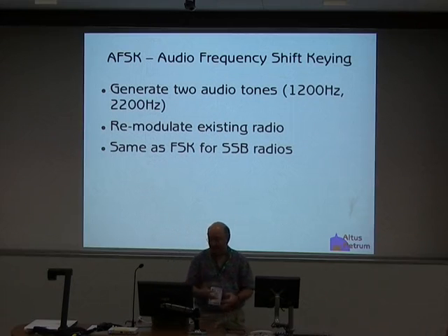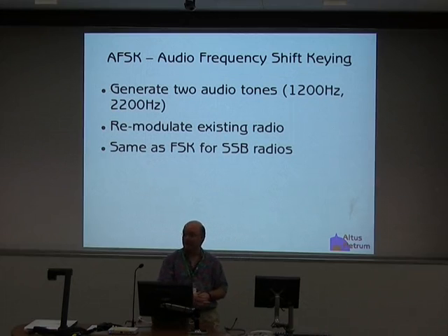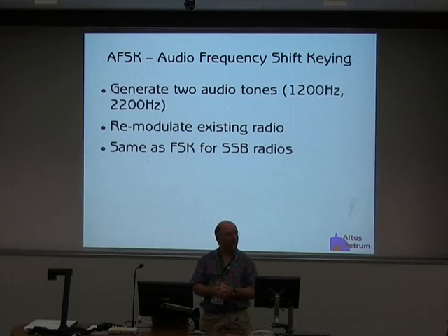Another one that I'm not going to touch on very much is audio frequency shift keying, and that's where you take an audio signal and put it into the mic input in your radio. So this is the old AX25 disaster, where you'd take an audio signal out of a Bell 202 modem and feed it into your FM transmitter. Well, if you feed it into your single sideband transmitter, you're just taking an audio signal and mixing it with your transmit signal, and that just turns into frequency shift keying. So that works pretty well.